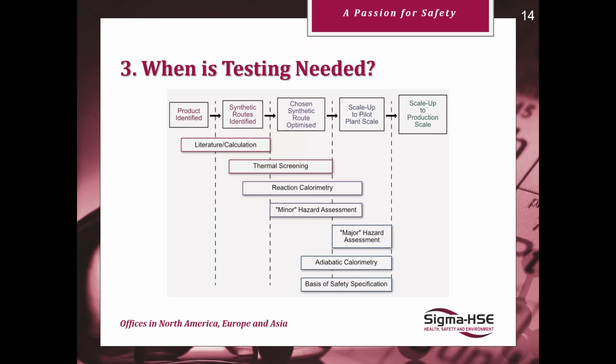And then the final kind of area of testing at this point would be some adiabatic calorimetry, used to really precisely investigate reaction enthalpies of decomposition or reaction enthalpies, pressure rise rates, and temperature rise rates for relief system design, and having much more certainty around the controls required in place to ensure that your desired process can come off without a hitch really when going to production scale.